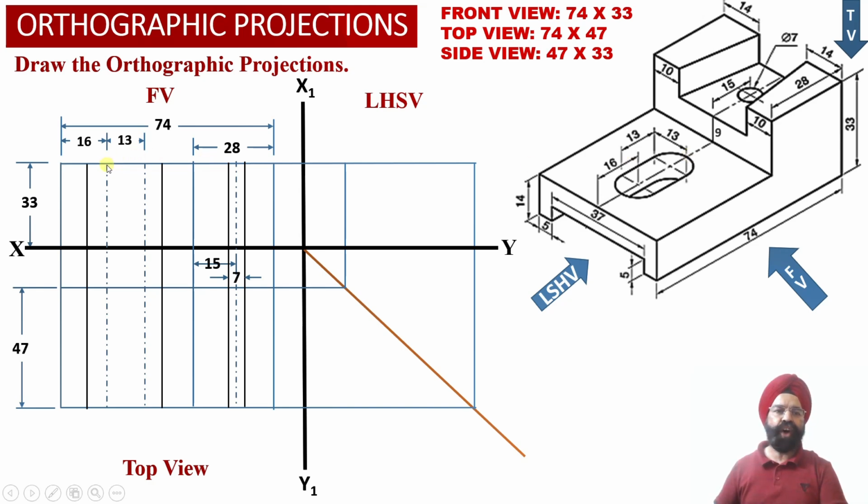So now we have taken an offset of 6.5 millimeter to the left hand side of the left side center projector line. Similarly, we have taken an offset of 6.5 millimeter towards the right hand side face of the solid from the second vertical center projector line over here, so that these two black vertical projector lines which we have obtained are going to depict these two extreme ends of this elongated semicircular slot, which is lying in the horizontal web, that is element number 1 over here.